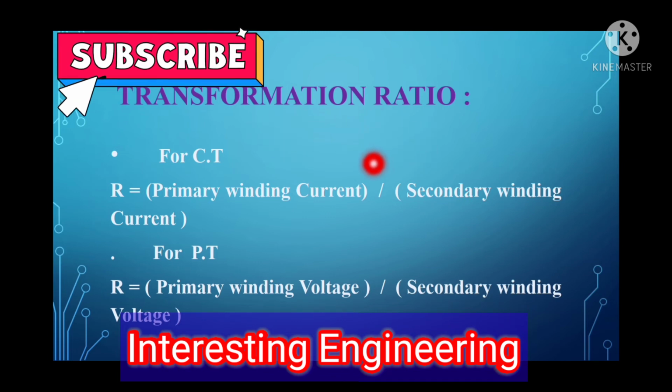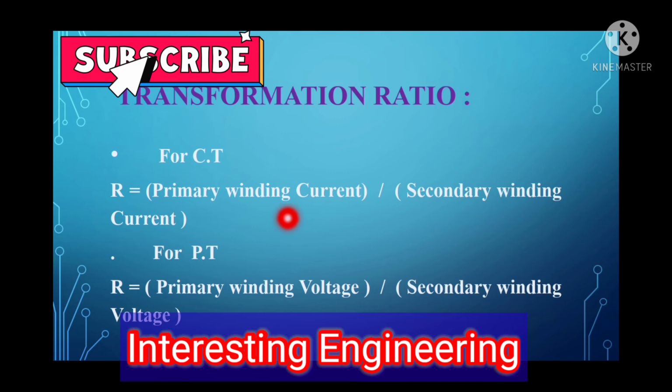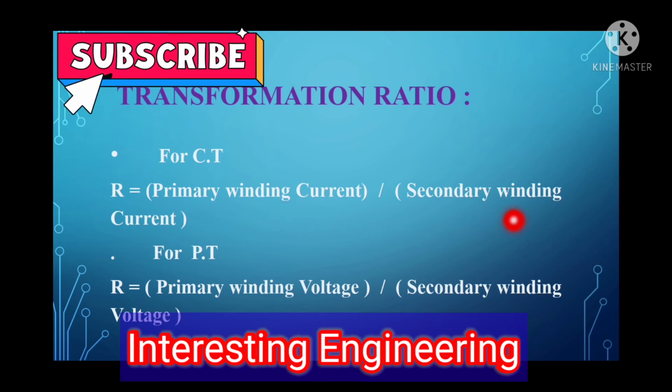In transformation ratio, the ratio differs for both types, for both current and potential transformer. In the case of current transformer, transformation ratio is represented by capital R, and it is nothing but the magnitude of primary winding current divided by magnitude of secondary winding current. So when we make use of a current transformer, the transformation ratio is the ratio of magnitude of primary winding current to magnitude of secondary winding current.